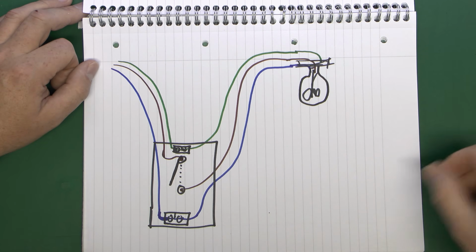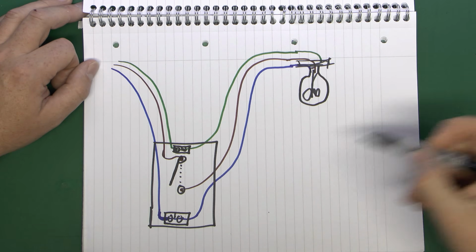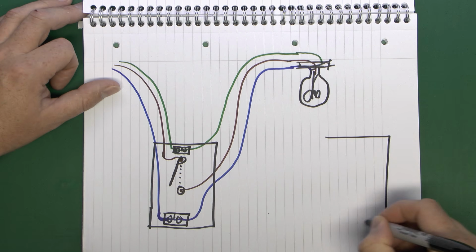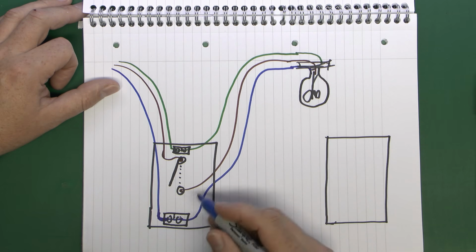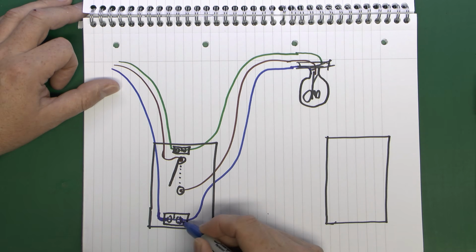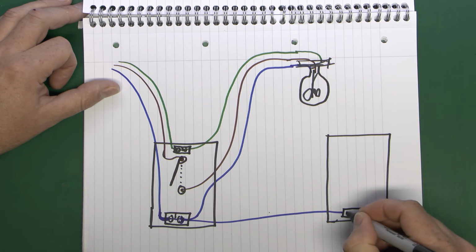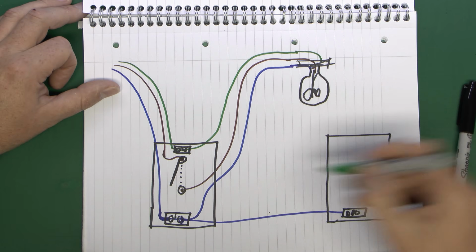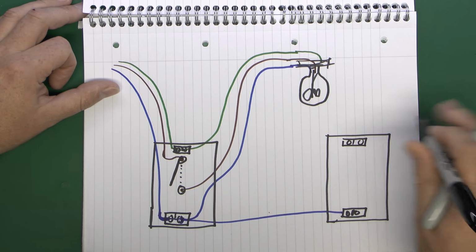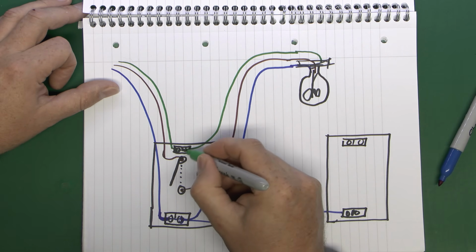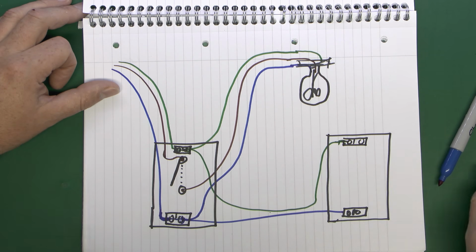Now, as before, we're going to want more than one light in our house, so just as with the previous diagram, we can extend all of these wires to another switch in the next room. So here's the other switch in the next room. And all we've got to do again is the 3 cores. So the neutral comes from our neutral connection here, so that will just go straight across. And of course in here we're going to have another terminal block there just for the neutrals. Earth is going to be the same, so again we're going to have a terminal block here for the earth, or the protective conductor. And again that would come off of the wires here, part of the same cable, and into the top there.